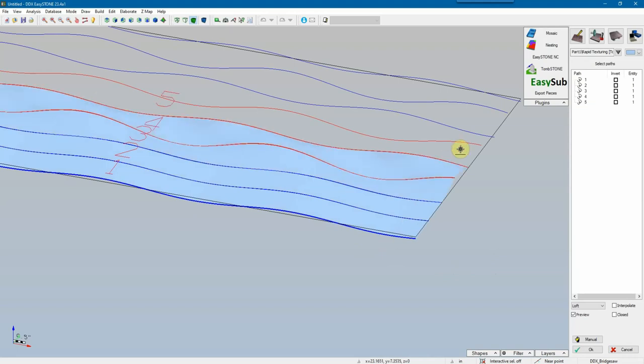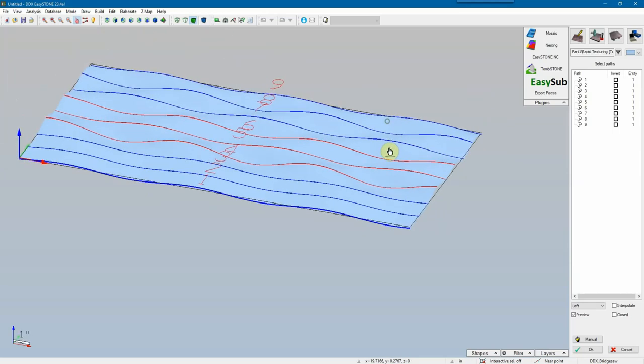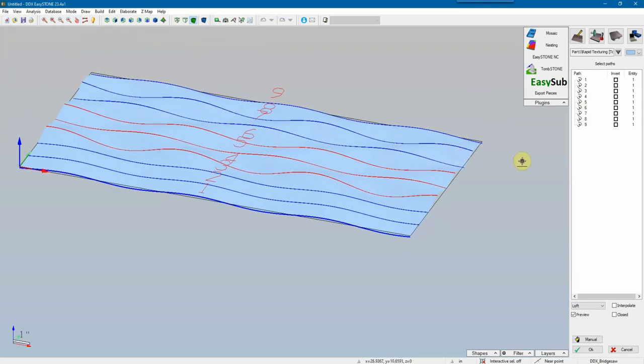surface is created. Now it's important to note that lofting a surface can start to consume processing power. This is a mathematically generated surface. So the more complex of a surface you have, the more time this is going to take. So as long as you're seeing the preview generate, it's okay to click on to the next path. Once I have all my paths selected, I say OK.